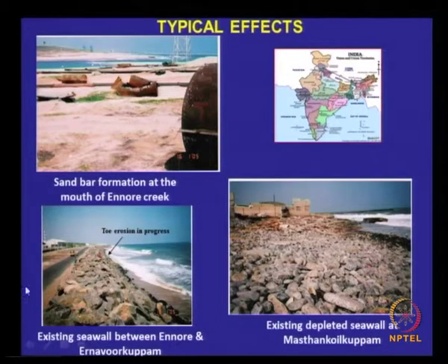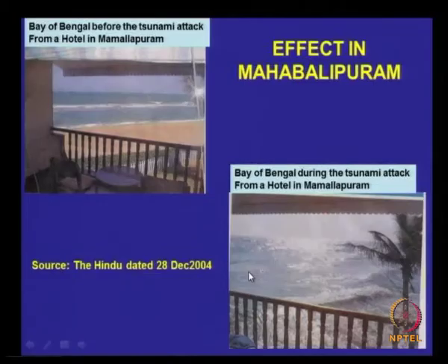When it is retreating, going back on the landward side of the seawall, these are all soft soil, it is only sand. With the velocity that is created, this will drag, and also there is some amount of drawdown here. All this will pull the sand inside, creating toe erosion, and there was a lot of damage to the sea walls, which we will see later.